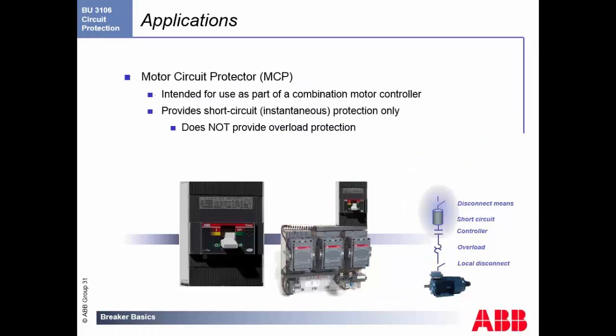So as we talked before, the motor circuit control right here is all inclusive into our T-Max breaker here. So this is a typical setup that you're going to see where you have the disconnect and the short circuit. So this is providing the LSIG curves that we talked about earlier. The power is coming in here, so we're looking for any problems down the line with this motor. Catastrophic problems. So winding breaks and you're starting to short. You're dropping neutral. Somehow your two phases get caught, and believe it or not, I've been out in Arizona on the surface mines, and they talk about all the wildlife that seems to creep into this cabinet, and everything's fine until they cross over phase, and then you need this to make sure that your motor doesn't pop.